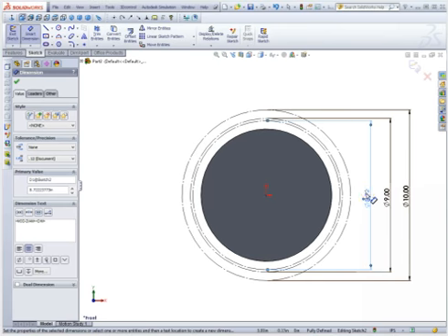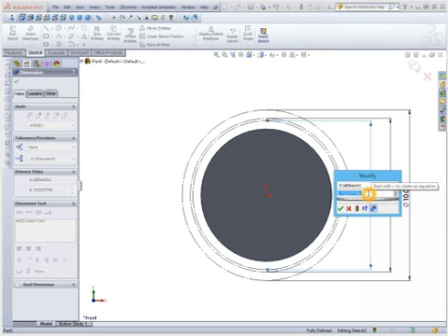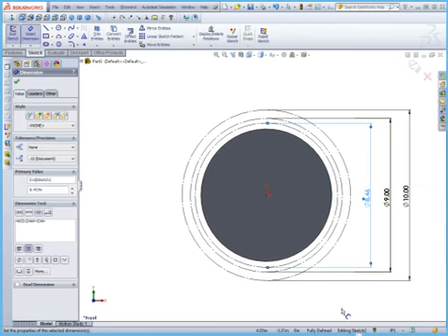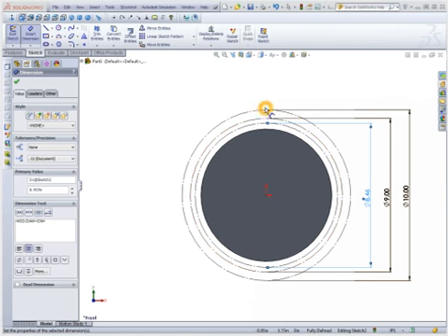And the diameter of our base circle is going to be the pitch diameter times cosine of the pressure angle. And so here you have to decide what your pressure angle is. We're going to use 20 degrees, so it's going to be 9 times cosine of 20, which is approximately 8.457. So here we have our 3 actual diameters that we need to define the rest of the tooth profile.